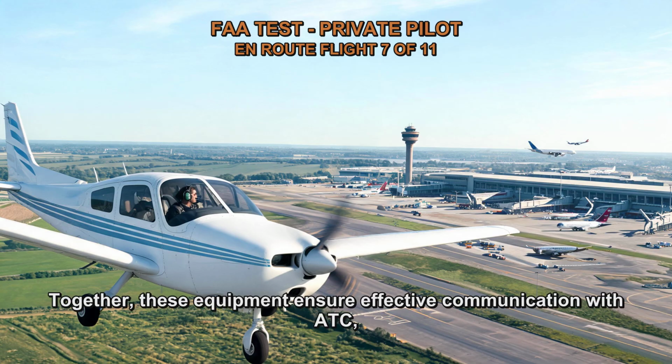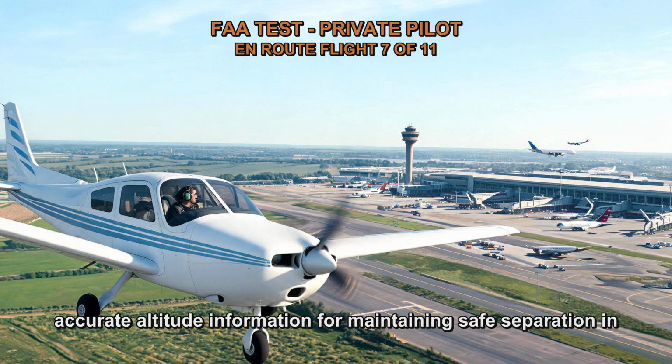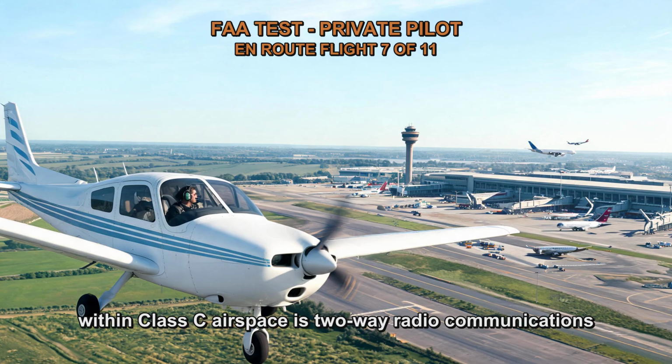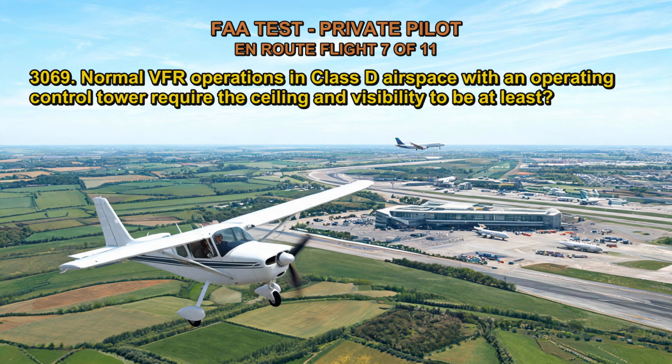Together, these equipment ensure effective communication with ATC, aid in aircraft identification and tracking, and provide accurate altitude information for maintaining safe separation in Class C airspace. Therefore, the minimum radio equipment required for operation within Class C airspace is two-way radio communications equipment, a 4096 code transponder, and an encoding altimeter.